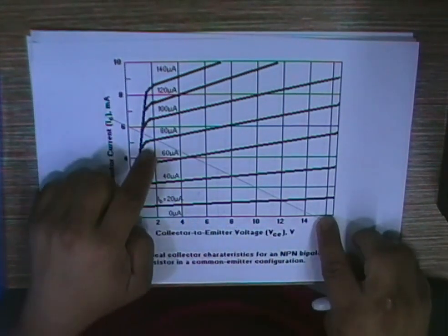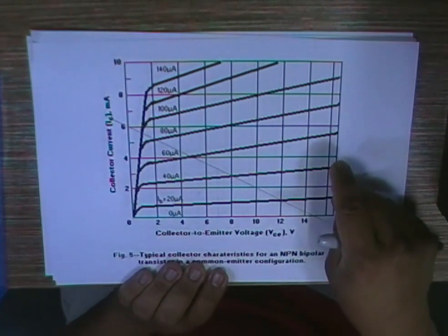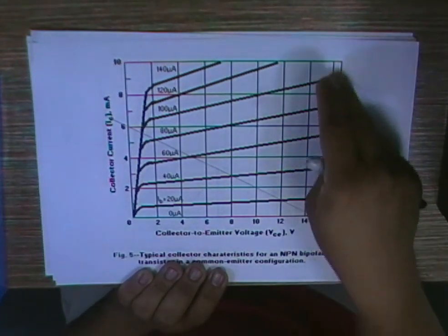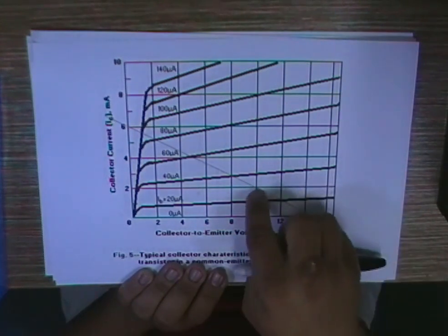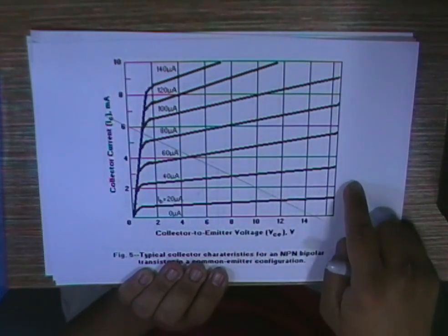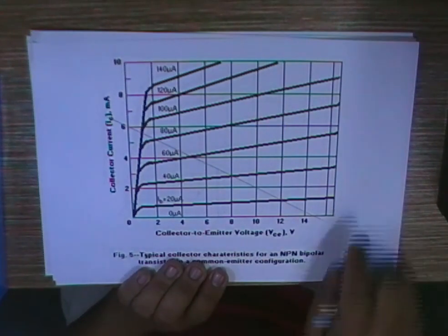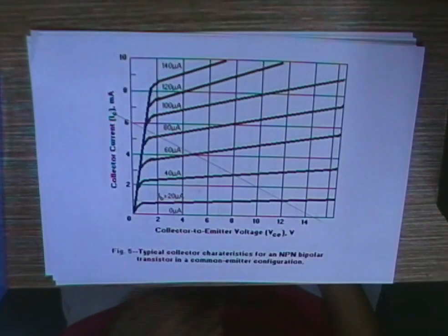And you can see also that this is the biasing current. In order to be safe, I have to make sure that my VB is around 1/3 of VCC. That's typically the idea on how to do the design of an amplifier using a BJT.